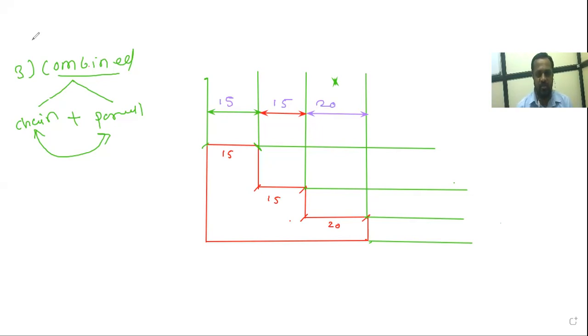Here I am going to draw. And in parallel dimensioning, we keep one line as a reference line, and from that line only we show all the dimensions. So this is first, then see this is the second. Okay, again. On this side, which dimension system are we using? On this side we are using the chain type. It is correct. See, this is the chain type.